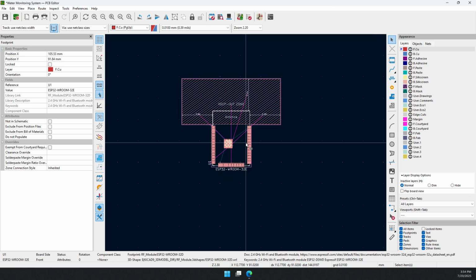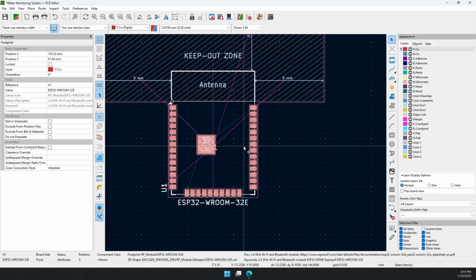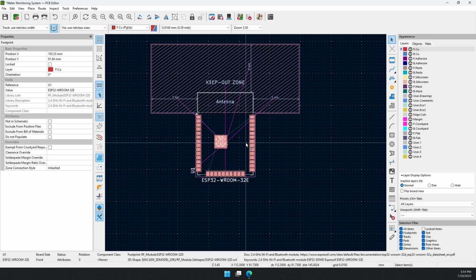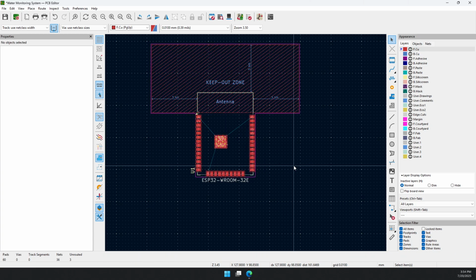Okay, so when we are done with the schematic, another thing we have to do is select the footprints. The footprints basically are what is actually routed on the PCB. So when I showed you the CNC PCB we did the last time, how it looked like, the tracks and traces, all of those are done here.